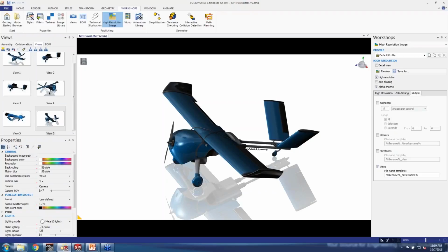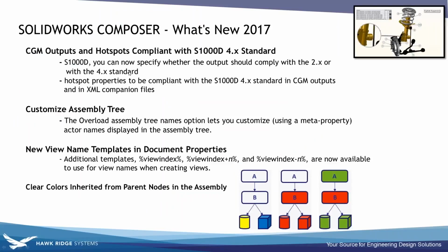And when you open up SMG number 2 and you want to control that, I think it was 16 through 32 or something like that, you can say, hey, we want to go ahead and change this. So the view name, let me pop that PowerPoint back up, view name or view index plus n or minus n. What that's going to do is that's a variable there. So the plus n, you can do nothing. It's just going to pull out whatever your current naming structure is.